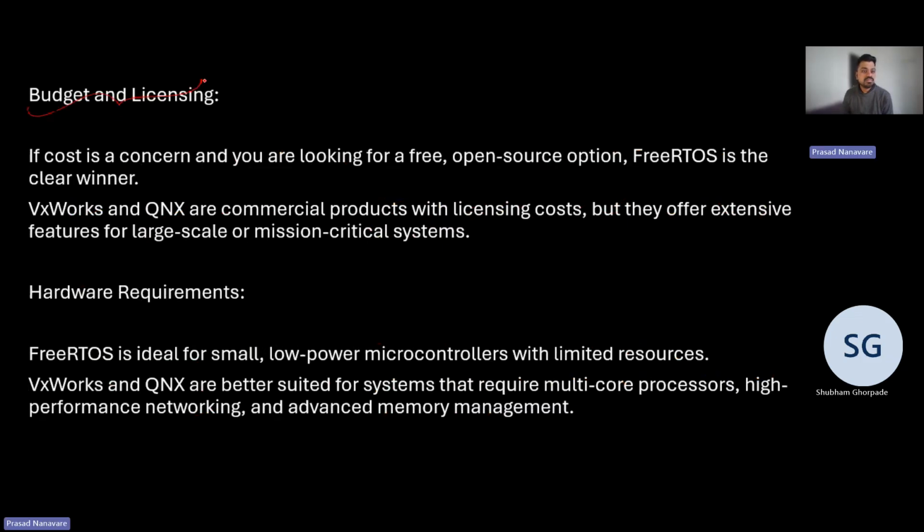Then if we consider budget and licensing, if cost is a concern and you are looking for a free open source option, FreeRTOS is the clear winner. VxWorks and QNX are commercial products with licensing cost, but they offer extensive features for large scale or mission critical systems.